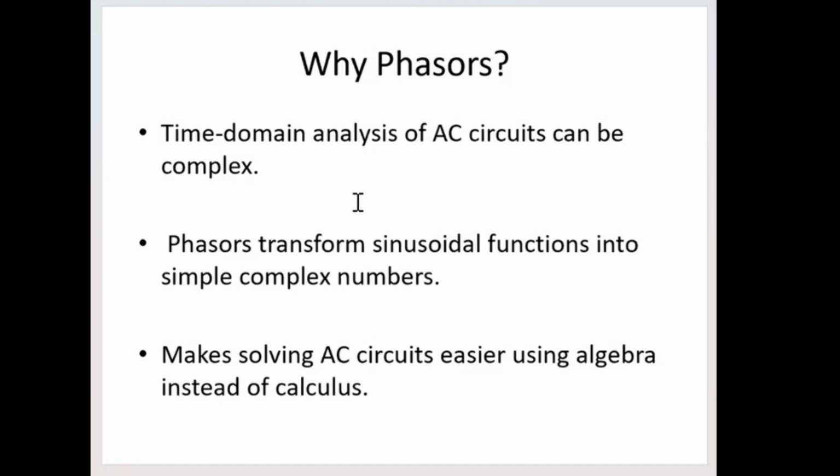So using this concept of phasor and transforming this sinusoidal function into a simple complex number will simplify the analysis of AC circuits. It is like we avoid solving differential equations if we are using phasors, and we only need to handle and manipulate algebraic equations, so it literally simplifies everything.